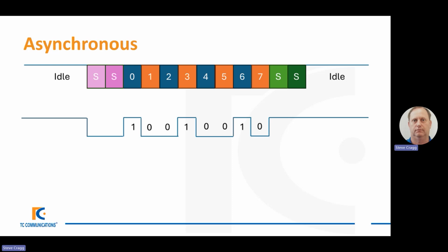So you can see that as it comes in, it sends 2 start bits. That means that the receiving device can look for an idle tone. Typically, the idle tone is at least 3-bit lengths long. So it can look for a high of 3-bit lengths.